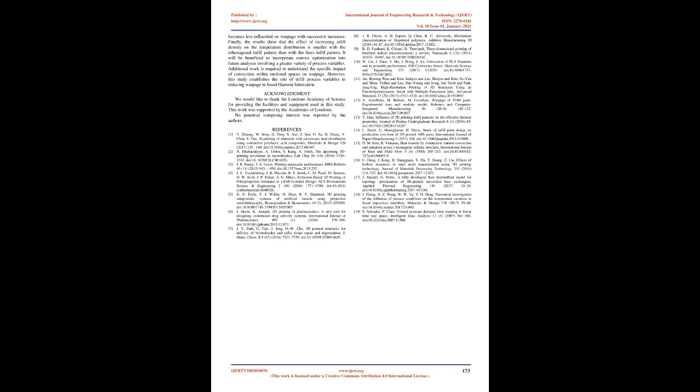This indicates that for both patterns, the heat flow trajectories for disks with the 20% and 30% infill densities are more similar than those with the 10% and 20% infill densities. Thus, at high infill densities, an additional increase results in a smaller effect than an additional increase at a low infill density. Therefore, the effect of increasing infill density is reduced for every additional increase.